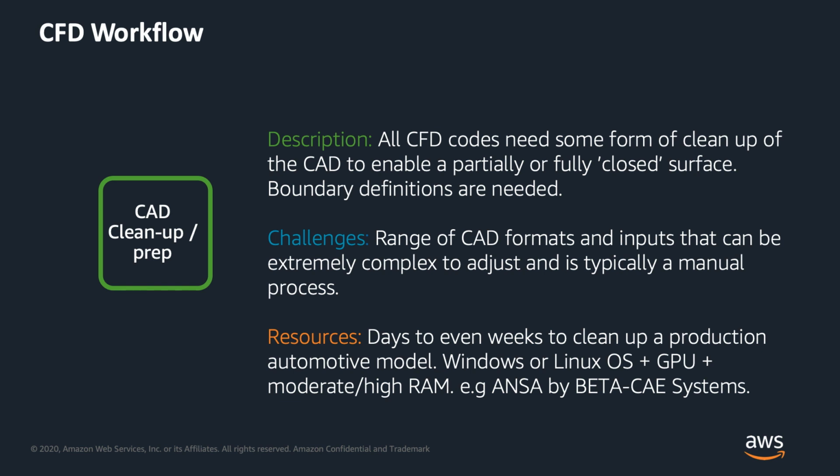You also typically need to do some definition of the boundaries, whether it's simple reporting of forces or defining where porous media, MRFs or fans are. The challenge here is simply that the input can be many CAD formats from many parts from different organizations and subcontractors, and can be extremely complex to adjust. And it's typically a very manual process.